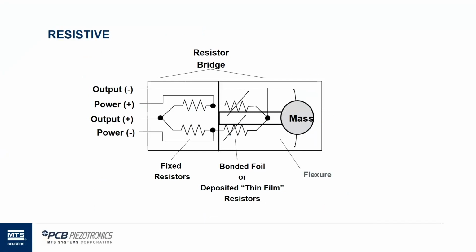And you see there, almost in the middle, those variable resistor symbols, and those are indicative of strain gauges, variable resistance type elements that we use to measure the strain. Not directly measure, but they provide a change in resistance due to that strain.